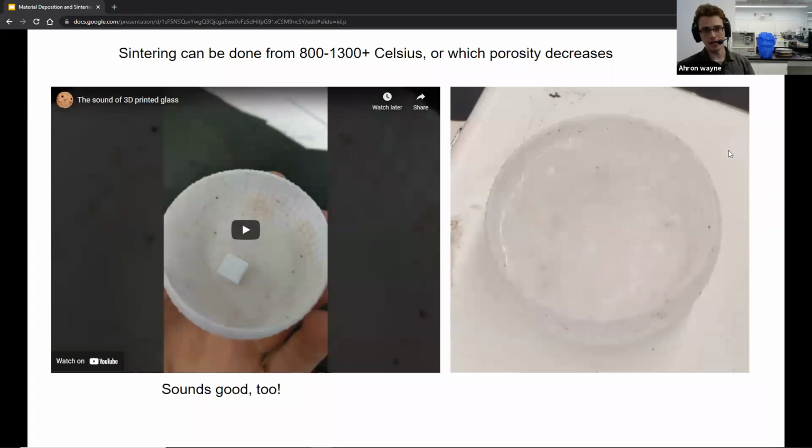So there is a guide. The company that I'm using here has sintering profiles available, and then I just modified mostly the peak temperature based on the experiences in my oven. Because the temperatures are very sensitive, most people are going to want to try the stock instructions and then just tinker with it a little bit until you get the properties you desire.